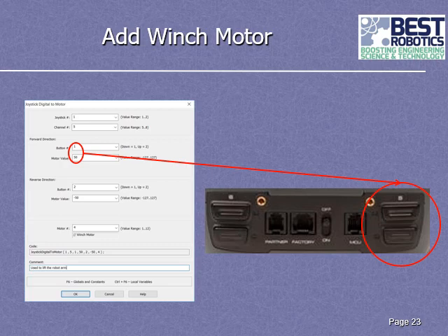Since the range of values that you can put in here is -127 to 127, what that's saying is it's going to be moving in the plus direction about a little bit more than a third of the speed with which that motor can go. And this is something you can play with. Once you get it all going and you realize, oh, it's either going too slow or too fast, you can simply double click on that function and change this number to whatever you need it to be. Sometimes you have to play with it a little bit to get the exact right number.